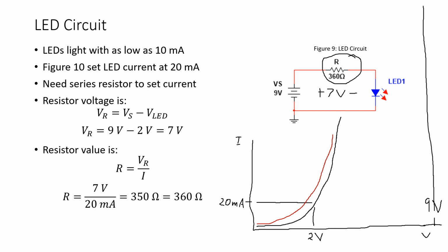So in this presentation, we looked at the PN junction used to construct a junction diode. We looked at the diode when it is forward biased. The depletion region is narrow, and the diode will conduct provided that we overcome the barrier potential of 0.7 volts.